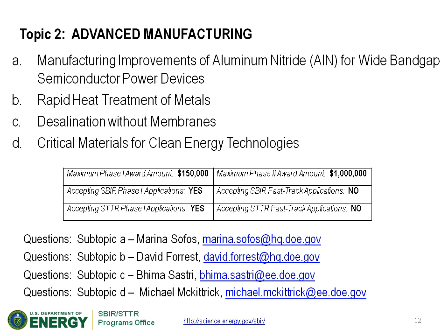And what comes with that is energy savings in the form of a higher efficiency process. Also, another benefit would be, in some cases, a reduced amount of oxidation of the metal because it's being heated, even if it's heated in air, and cooled in a very short period of time, giving you a higher yield.